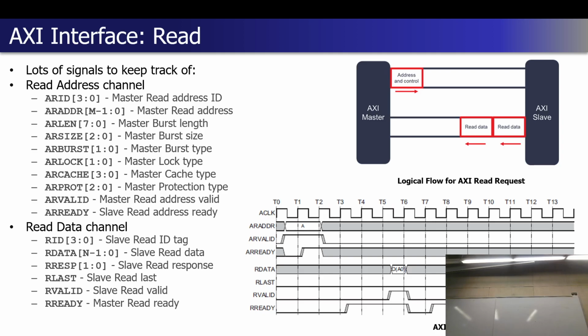I am specifying, as what was initially the sender, that I am ready. I know that I have valid data once I see that valid data signal go high from the receiver side. That indicates a single beat of a burst transaction happening.